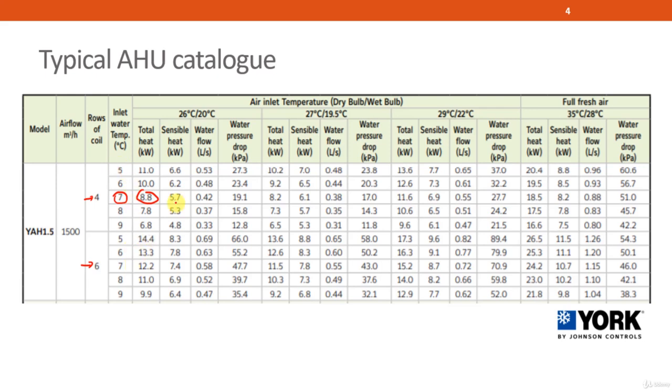Alright, then the sensible heat, as I mentioned just now, there's sensible heat and total heat. So if it's able to satisfy the total heat but unable to satisfy the amount of sensible heat, then you will have to maybe upsize the particular model.